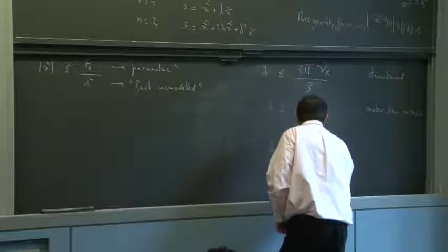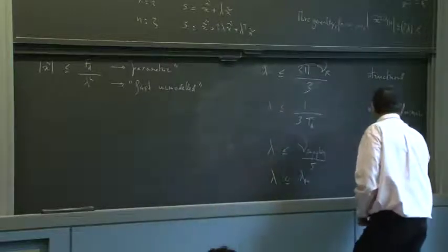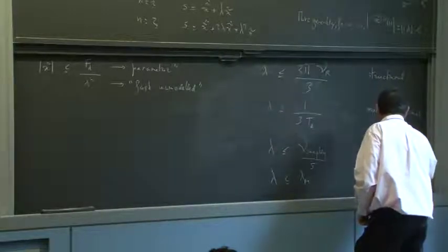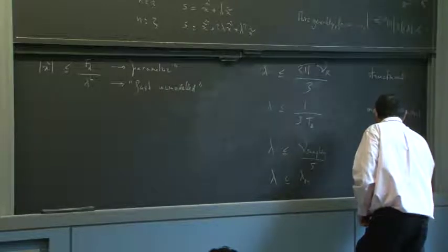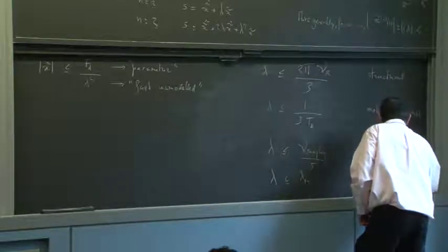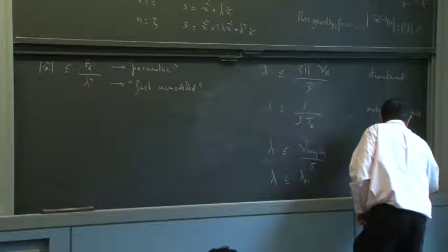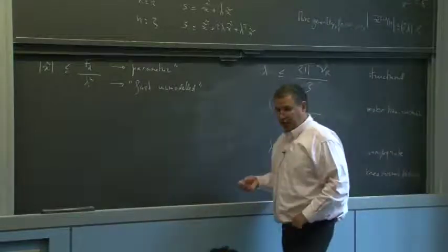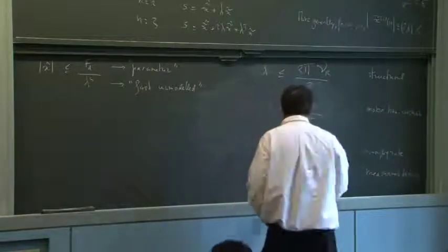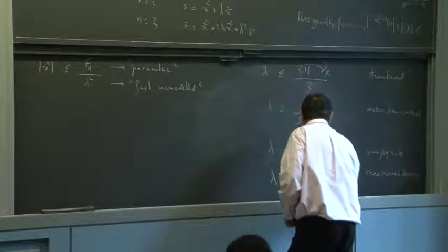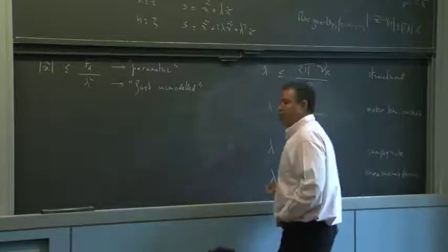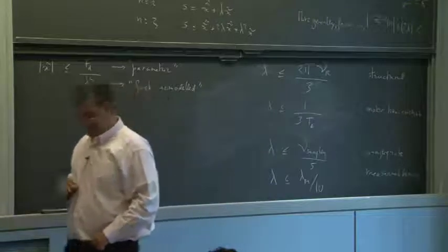So this is the sampling rate. Similarly, you could have measurement dynamics or observer dynamics. And as you know, if you play, for instance, with root locus and so on, you're quite sensitive to that, so maybe you want a factor 10 from that.